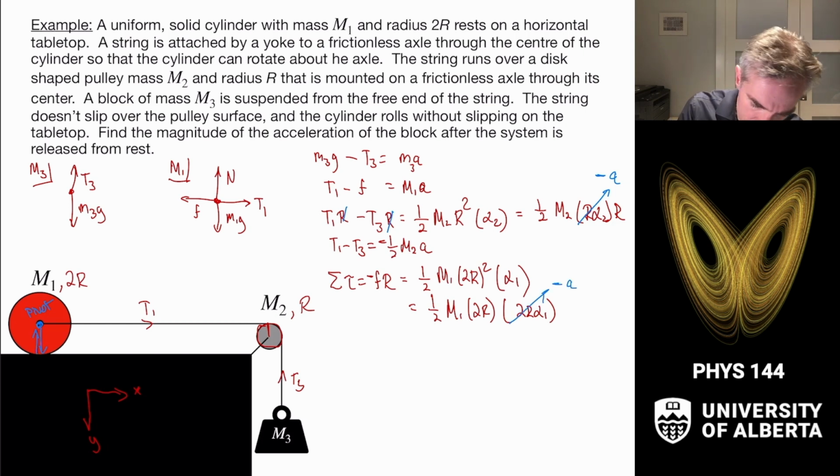And I'm going to just fix up one little mistake I made over here, which is the moment arm is f times r times 2, because it's 2r. It's the radius of the object, but we've called it 2r in this problem. It's maddening. 2fr. And this will cancel out. So we get a 2 and an r and a 2 and an r, and then a negative sign cancels out.